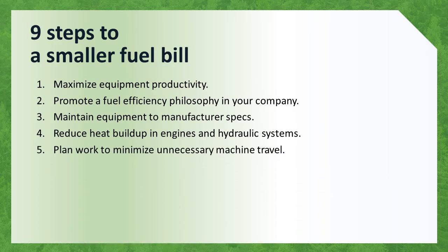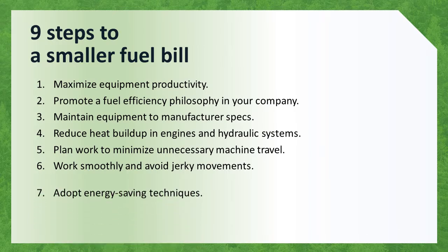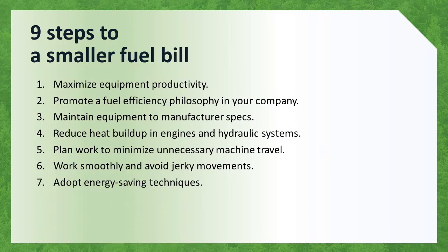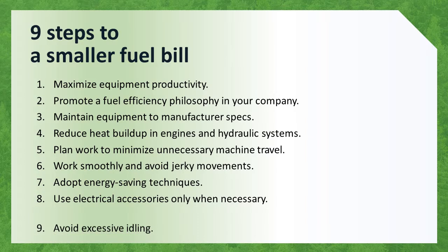Plan work to minimize unnecessary machine travel. 6. Work smoothly and avoid jerky movements. 7. Adopt energy-saving practices. 8. Use electrical accessories only when necessary. 9. Avoid excessive idling.